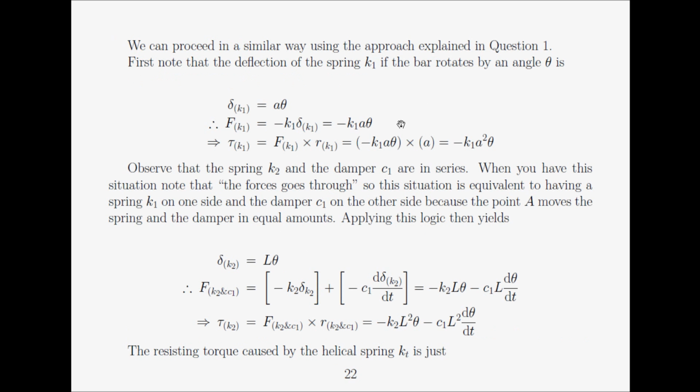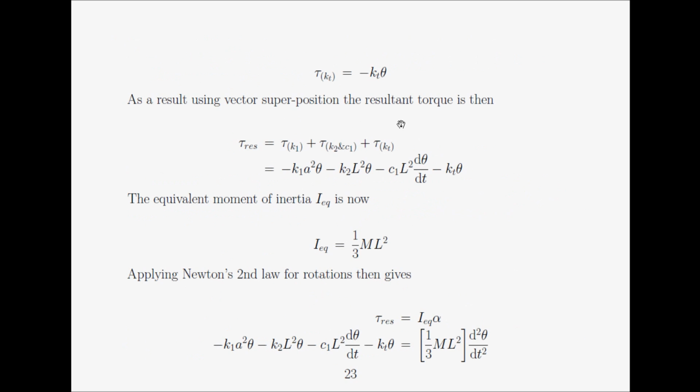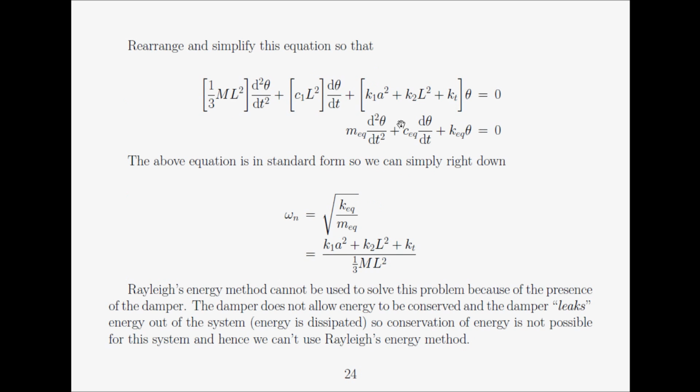We get an equation. We then rearrange that equation as a homogeneous differential equation, like we have at the top, and that particular homogeneous differential equation is the standard single degree of freedom system for a vibrations problem. Essentially, once we have it in that standard form, we have solved to a very large extent the problem.